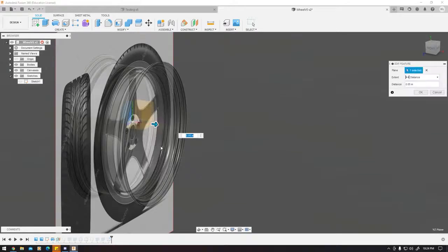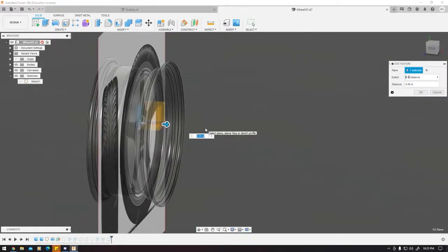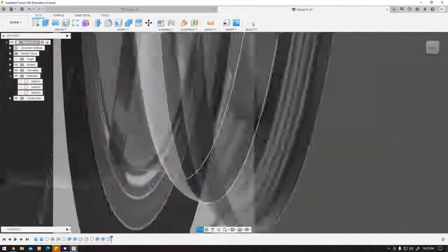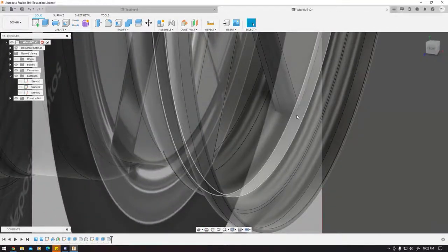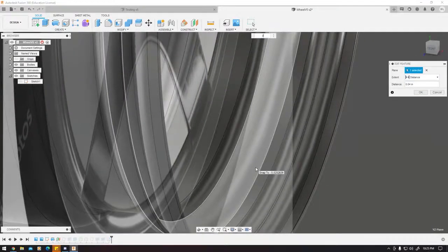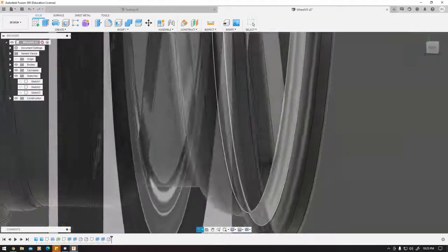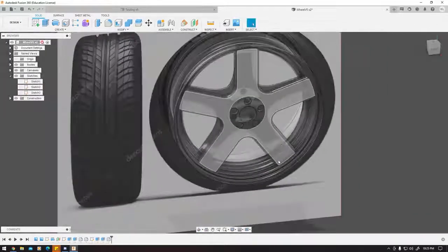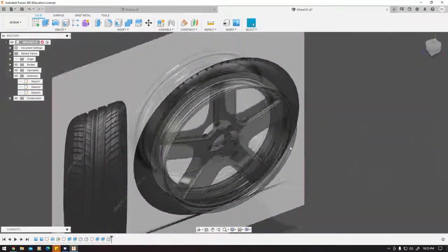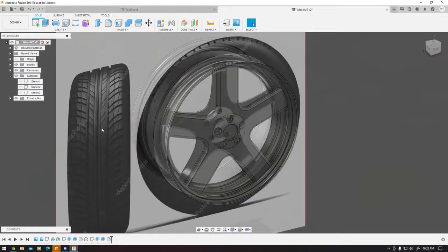I can make it go in by, let's say it is 0.05, we're going to make it 0.04, go in, press enter, and you can see it went from out here to in here, but that was a little too much, so I'm going to do 0.045. It went in. You can play around with it, but it's a cool point to make when you're dealing with offsetting your objects from planes.